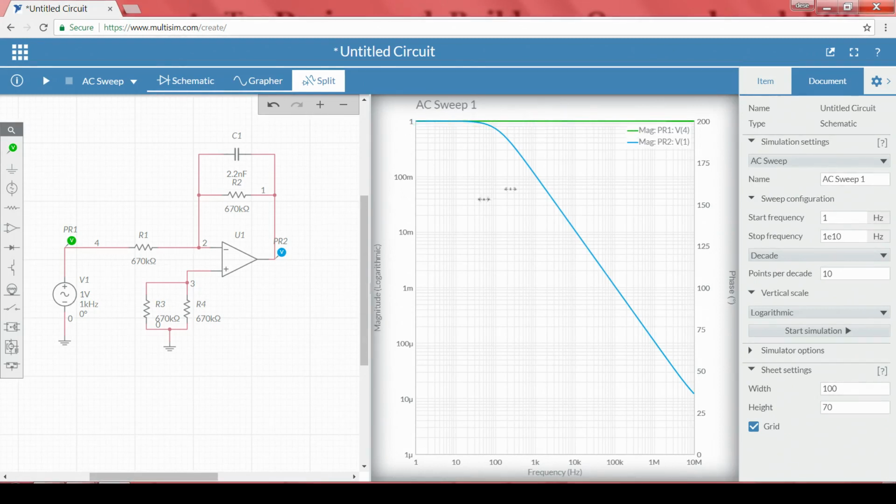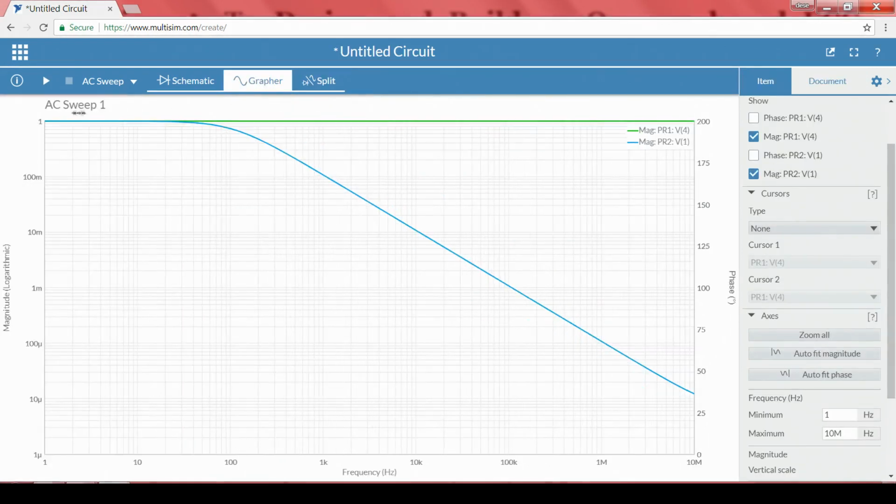That means both have the same gain, but after a particular frequency, if I closely observe, the output is attenuating, right, the magnitude is decreasing. But at what frequency? How do we calculate our cutoff frequency? As we know, we have to consider the 3 dB line. Since the magnitude is 1, the 3 dB line will be 3 dB below the 1.